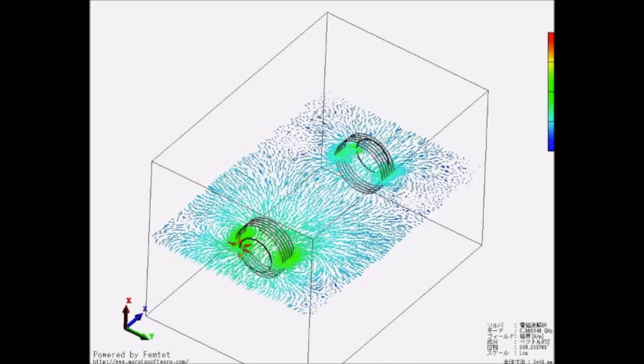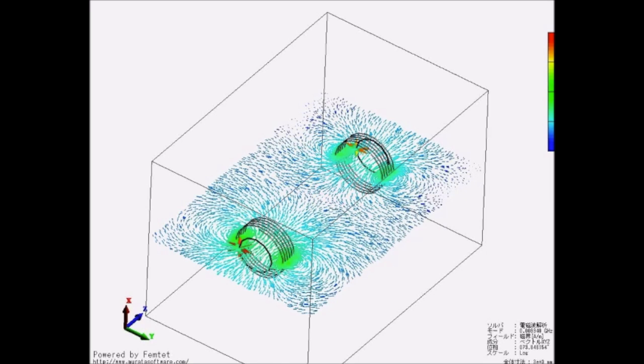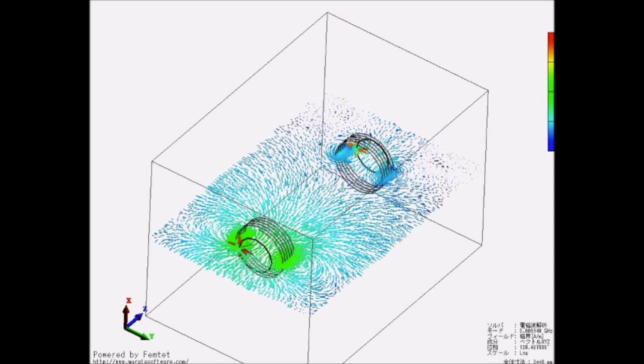To conclude, the mains voltage is converted into an alternating current signal, which is then sent to the transmitter coil via the electronic transmitter circuit. The alternating current flowing through the transmitter coil induces a magnetic field which can extend to the receiver coil, which lies in relative proximity. The magnetic field then generates a current which flows through the coil of the receiving device.